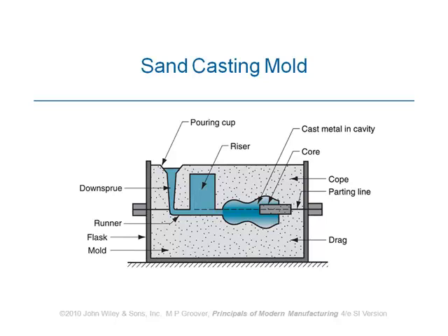As you see, it's the runner which leads into the cavity and also into the riser. And we have got to design it in a way that the runner and the gating system has a cross-sectional area which is sufficient for the process. Meaning what? Suppose this part of the gating mechanism is solidified before this cavity and this cavity are solidified, what happens? This bit solidifies before the cavity and also before the riser.